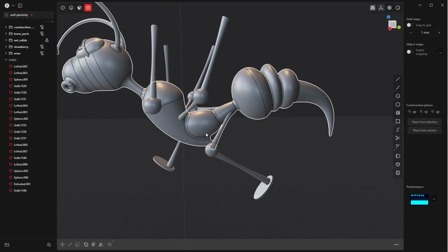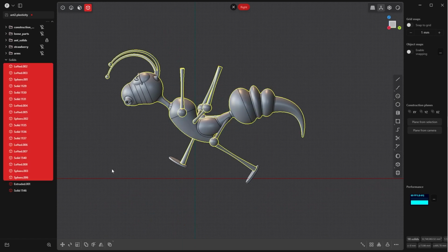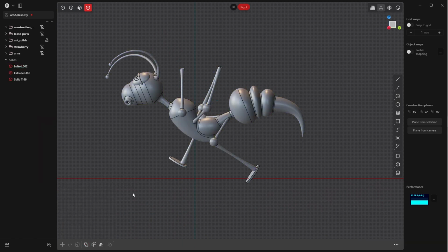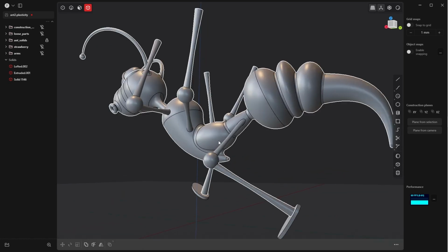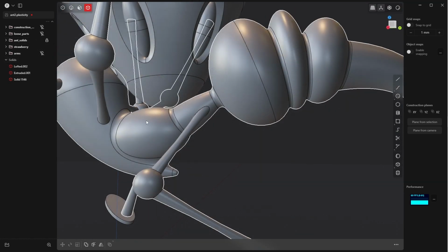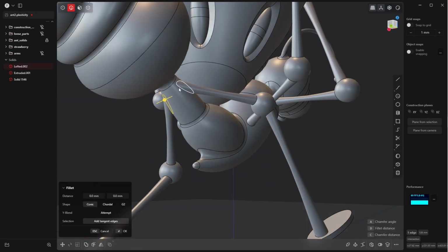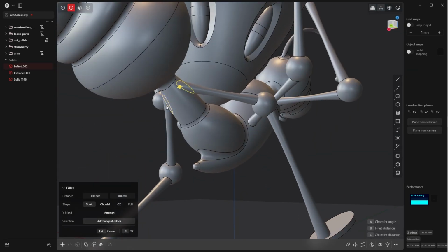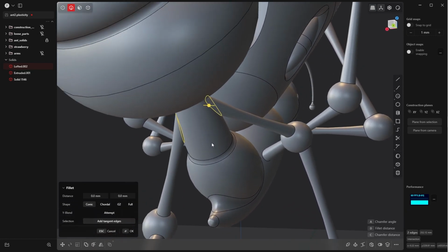That's what I wanted. Now we can repeat this, selecting all the parts, and press Q twice, and we have a successful union Boolean operation. Can bring back the rest, keep on filleting stuff. Let's go to edge mode, and all the symmetry parts or similar parts which are on the other side should be filleted together, so we have similar fillets.